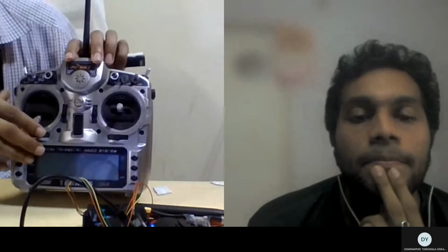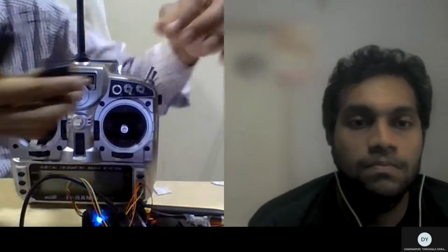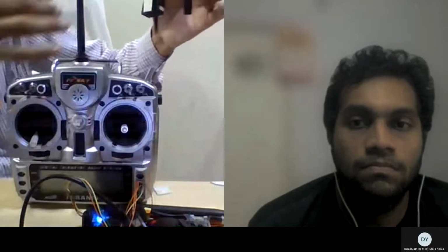Okay. First you should know any TX comes with one receiver like this. Okay, you have a receiver. This can work for 1 km, 3 km, or 5 km range depending on the model, but normally we recommend 3 km maximum. It's not to go more than that. Beyond line of sight is not recommended. If you change the antenna, or use some more modems, like long range modems, maybe you can improve your communication range. If I power both here, it will work, no doubt.